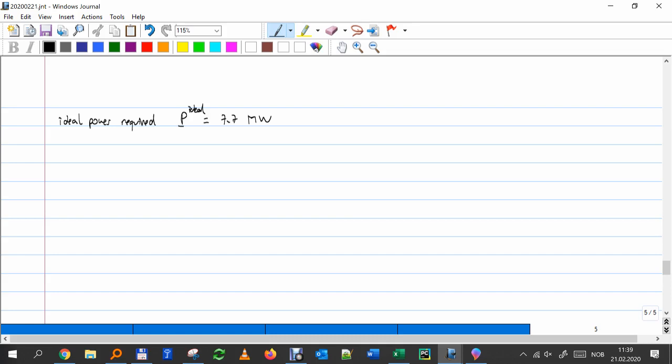Okay, page 62, 63, equation 246. So equation 246 is what we use. We don't use the chart really. We use this equation to calculate the outlet temperature. And we say here the outlet temperature divided by the inlet temperature will be equal to P outlet divided by P inlet, which is what we call the pressure ratio, to the power of n minus 1 divided by n.